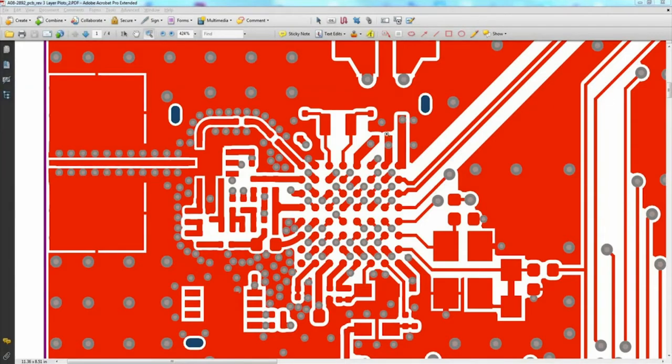Firstly, some basic understanding is desirable to effectively use the PCB design rules we will cover today. It is then easy to identify the undesirable effects that can arise and how to avoid them. The reason PCB layout becomes more and more important is because of the trend to faster, higher integrated, smaller form factors and lower power electronic circuits. The higher the switching frequencies are, the more radiation occurs on the PCB. With good layout, many EMI problems can be minimized and meet the required specifications.